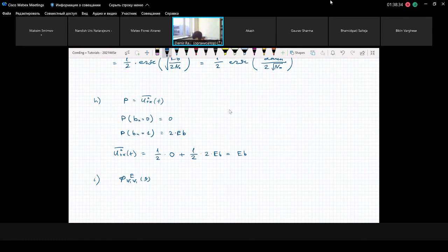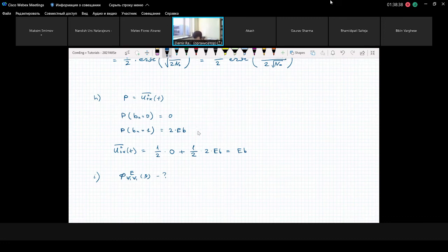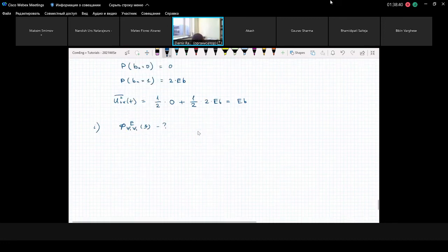I need to find the energy spectral density of the basis function, and the easiest path will be to take our basis function as it is, calculate the Fourier transform of it, then calculate the absolute value squared of the spectrum, and this is nothing else than our energy spectral density.